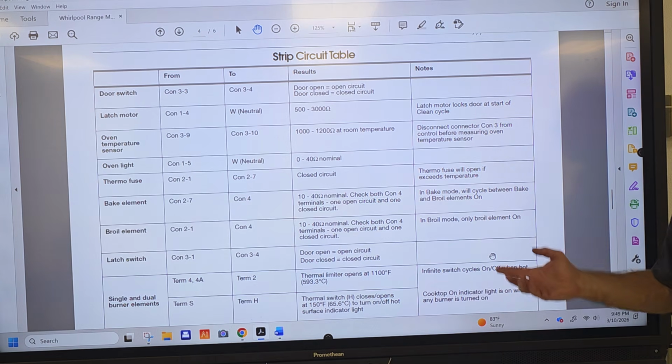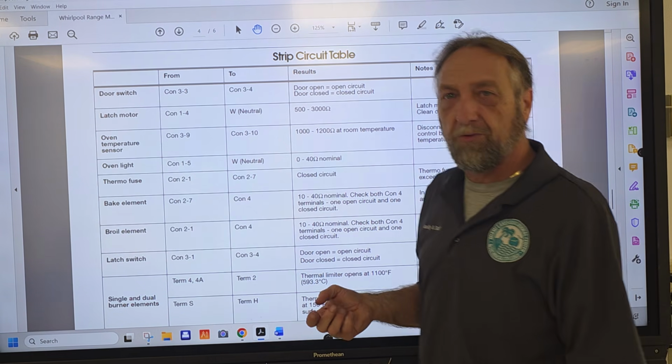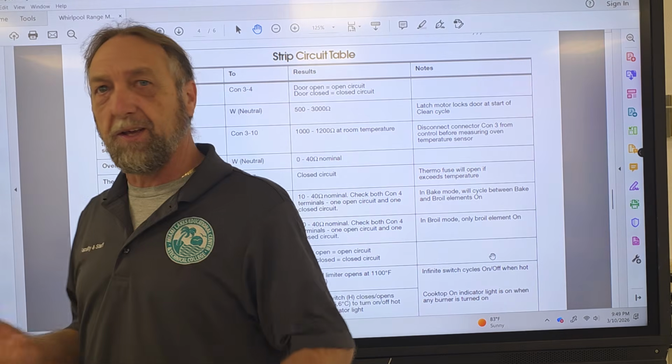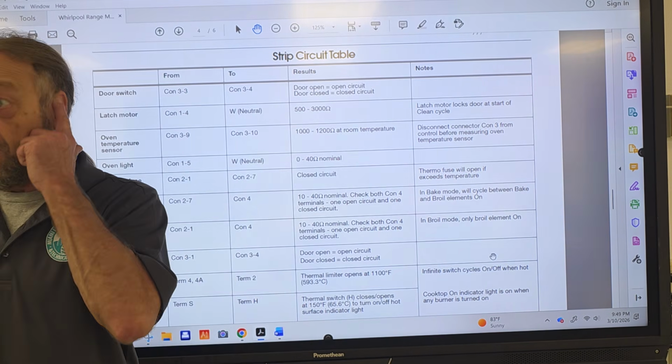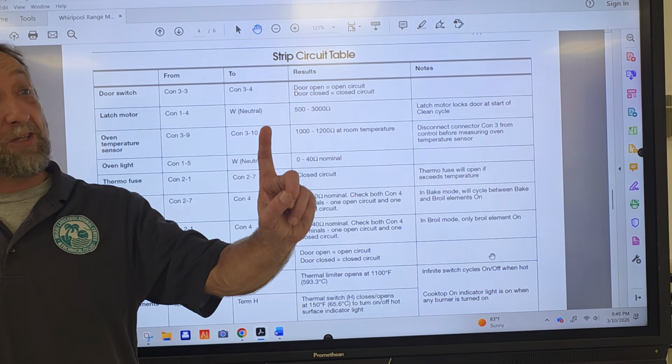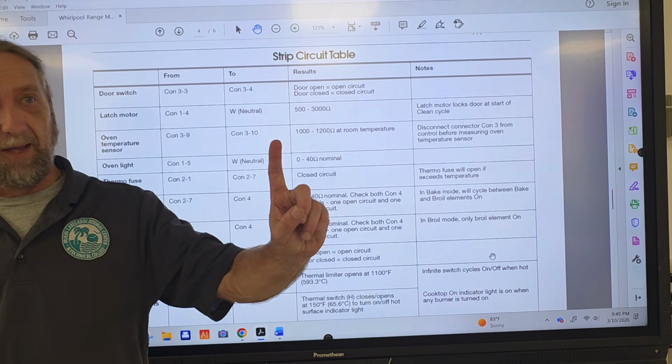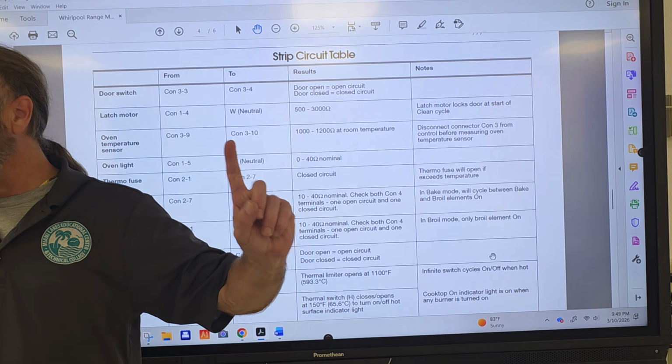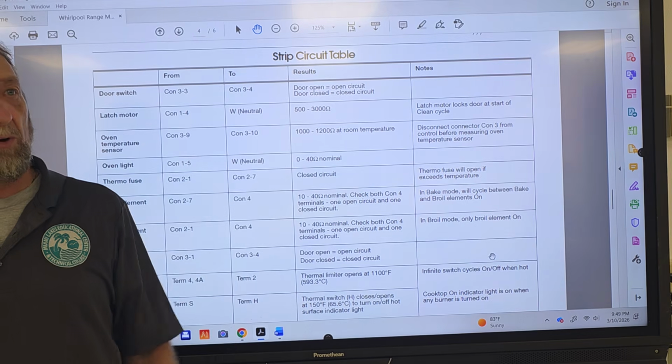Yeah. So if they were both 40 ohms, what's the wattage? Are they different wattages? No, because if the voltage is the same coming in and the resistances are identical, the output power is identical.